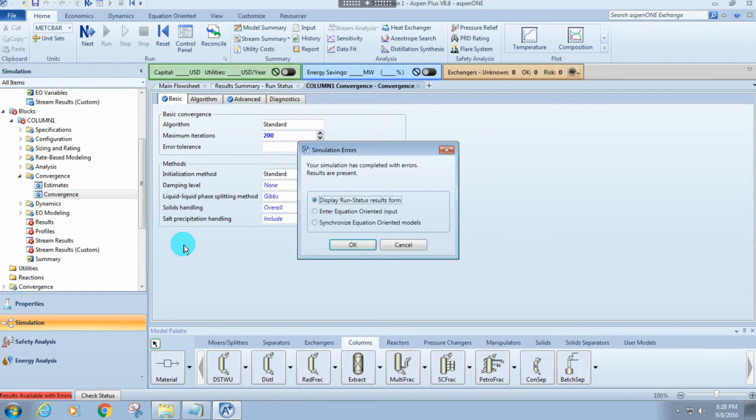Okay? And as you might already know, based on the hint of pressure swing distillation, there is an azeotrope between THF and water, and that's why getting a pure stream with one column is impossible. And ASPEN will tell you that. It won't tell you directly, but you might have to use your logic, use your understanding of certain unit operations to know that that's what's causing the error.